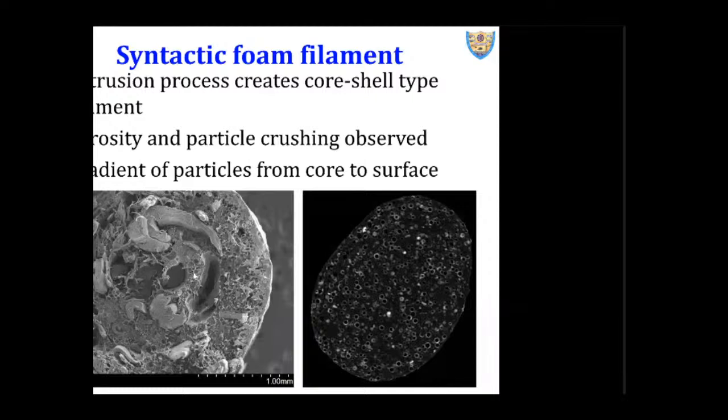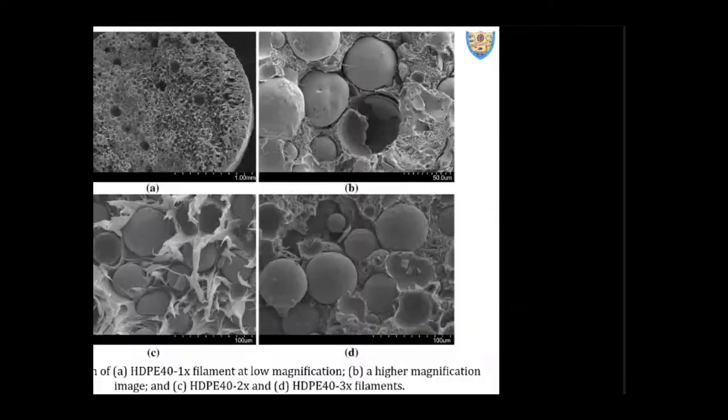A is our 60% by weight cenospheres in HTP. What do you mean by 60% by weight? By volume, probably it is around 73 or 74%. So by that amount, we could successfully load a particular resin. And what does that mean? If I say 75% by volume is my cenospheres, then only 25% is the matrix. So I can save 75% of the matrix if I can print this filament.